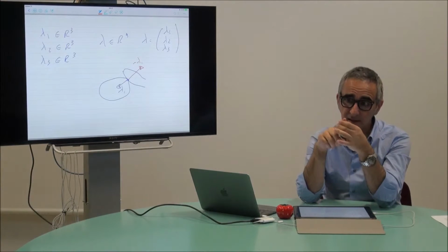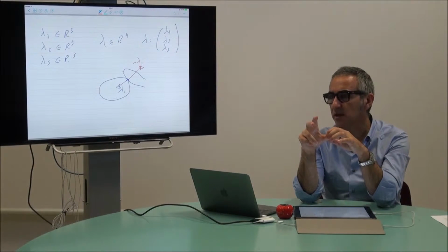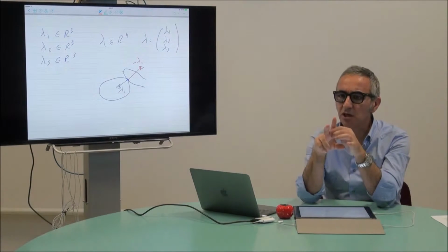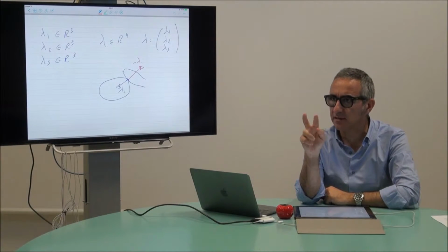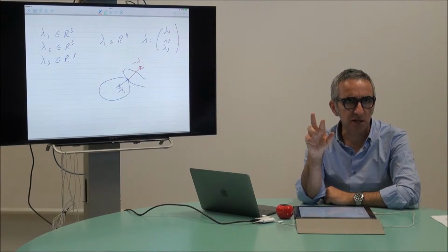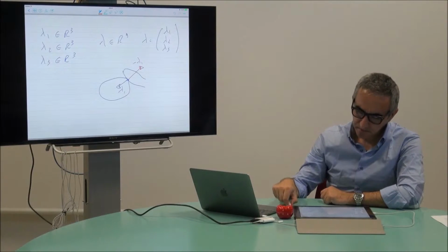So we can simplify the assumption and consider just 3 independent torques for each finger. For my index finger, for my middle finger, and for my thumb, I am assuming that I have 3 joint torques that I can independently control. So if this was a robotic hand, I have 9 motors, 3 per finger.